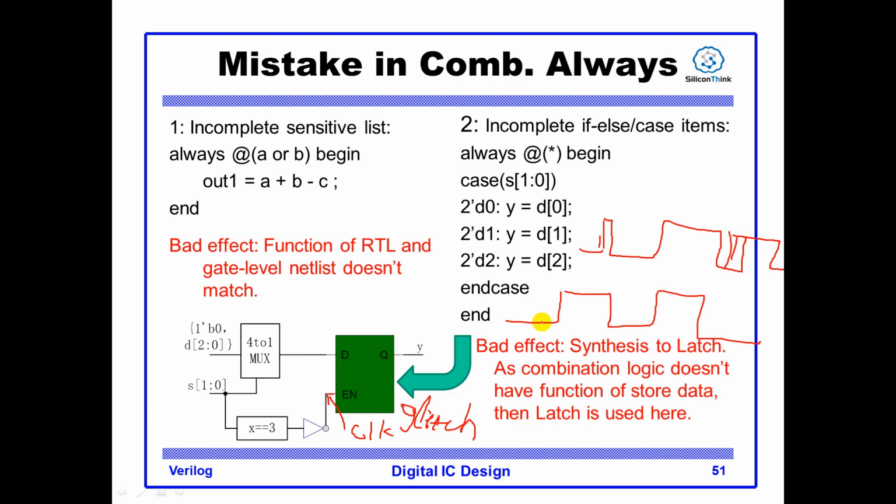So if you just connect the enable pin of the latch to the combinational logic output, there may be a glitch at this point. As for why there is a glitch at the output of combinational logic, you can Google it. If you can't find the answer, you can post this question, and I will reply to you.